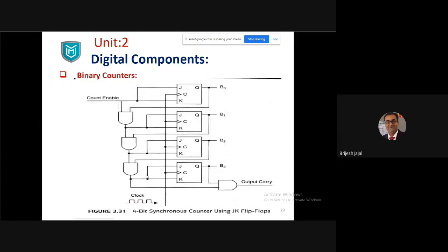I will come back to the circuit. If I say that this is a clock, you see the clock at the end of this diagram. This clock goes up. When it goes up, this signal is activated, and here I get the change. The new value will be shown here. It will blink here. When it goes down, nothing will happen. The next clock, when it goes up, again the new value will come. So it works like this.